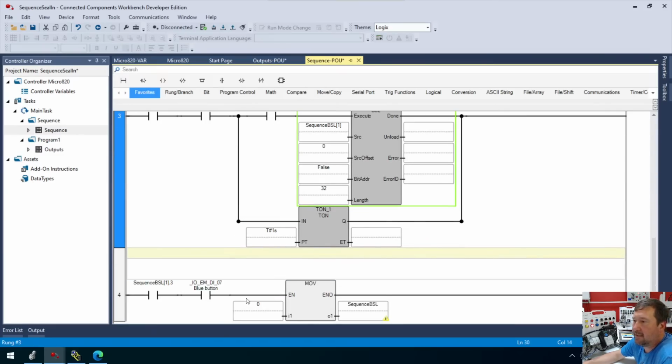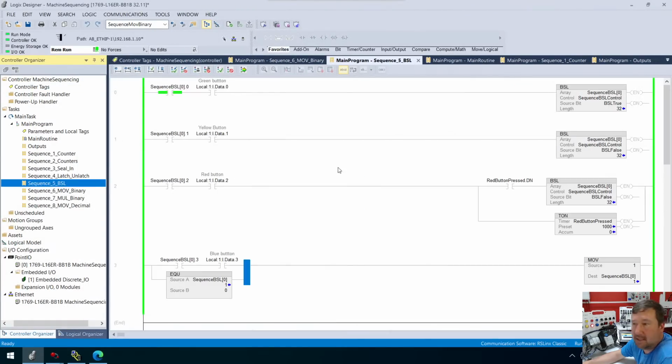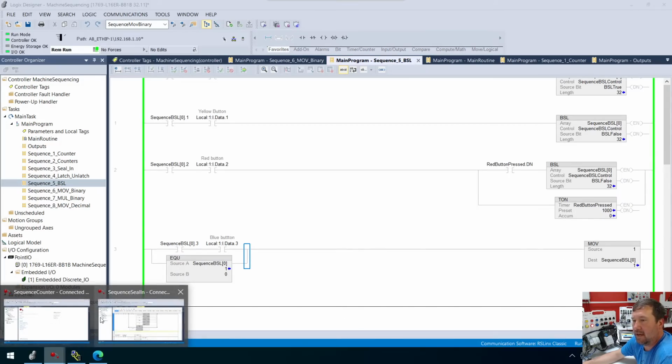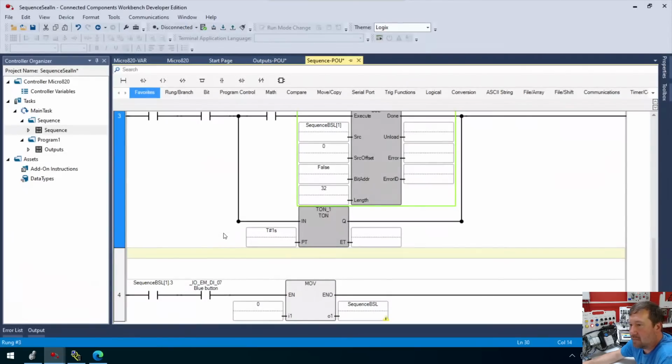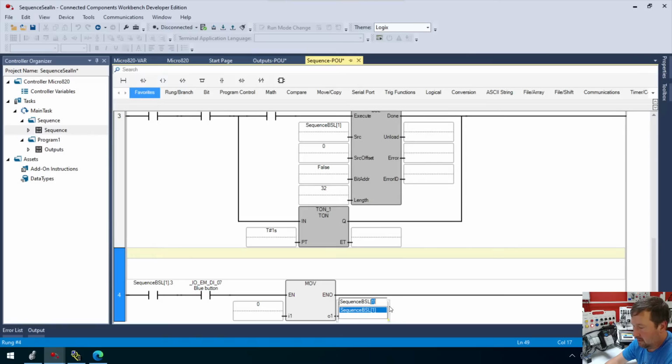And then finally, we are going to do this last one different. Let me make sure how I did this in Studio 5000 is, yeah, during that condition, or if it equals 0, then we're going to move a 1 into it. And we'll talk about why in a second. But all right, so we go back here. So yeah, in this case, this part is here, but we're going to be bracket 1 bracket, and we're going to move a 1 into it.